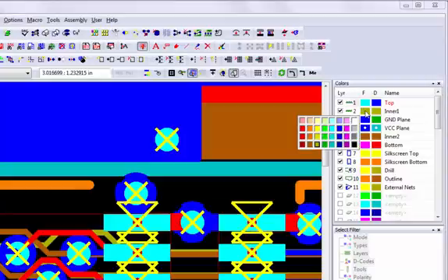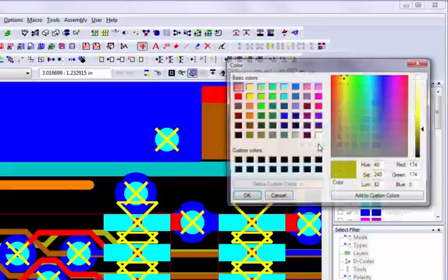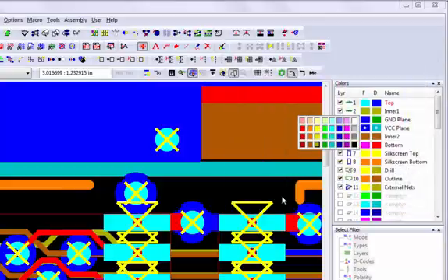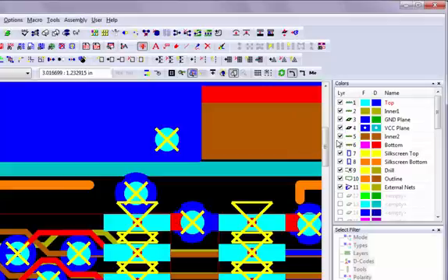You can control the color of the flashes and draws for each of your layers. To change one of the colors, click on it to invoke the color selector. Choose another color from those offered, or right-click on a color to open the standard Windows color selector that allows you to define a custom color. To dismiss the basic color selector without choosing a color, press the Escape key on your keyboard.